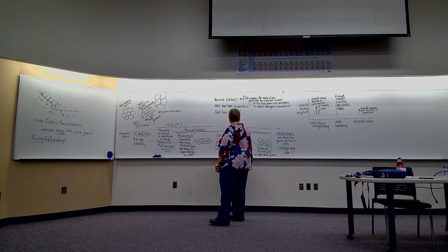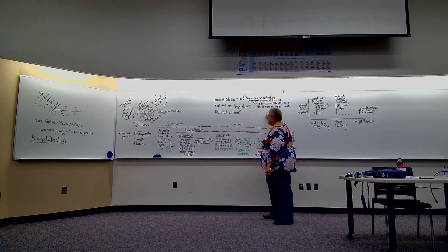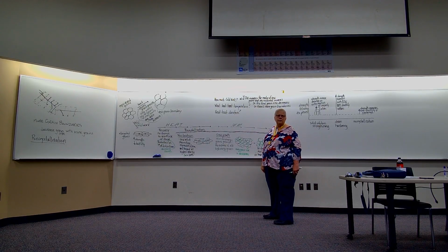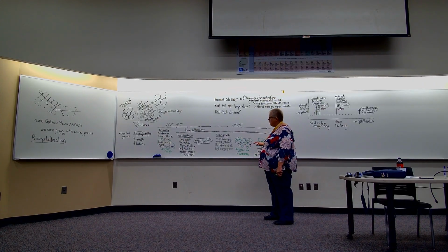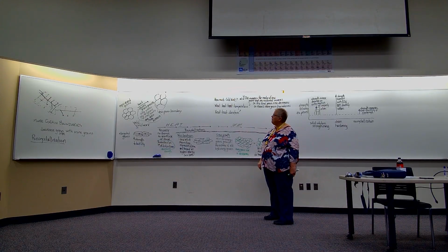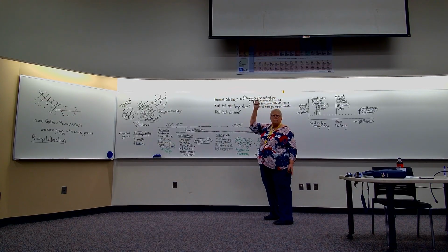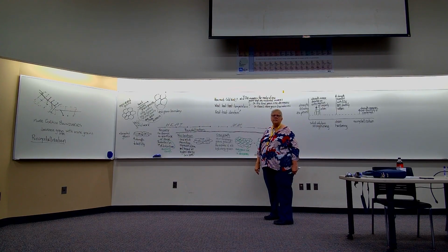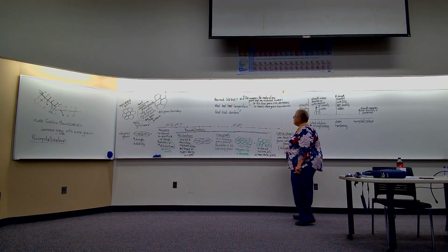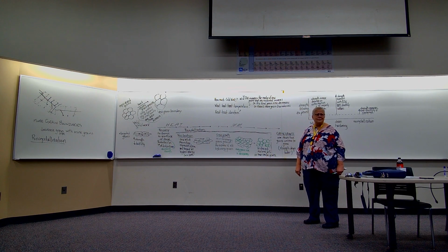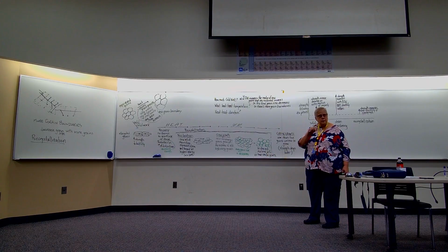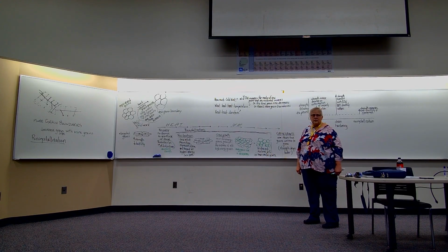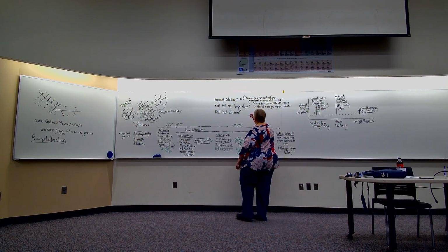The increase in strength with grain boundary area also has an upper limit. It has a big effect for a small increase in grain boundary area, but it levels off, and so this has an upper practical limit. But I'd like to get close to it, because here's a way that I can really increase the strength with this process. So how much cold work?